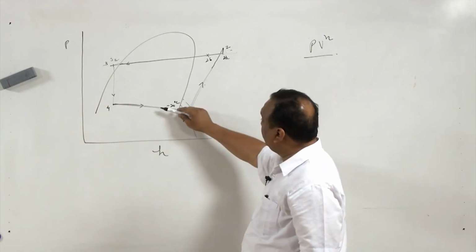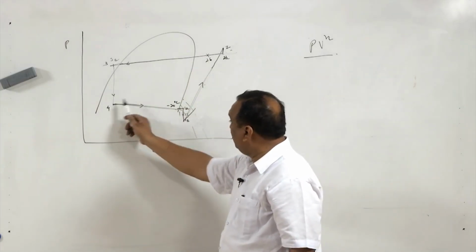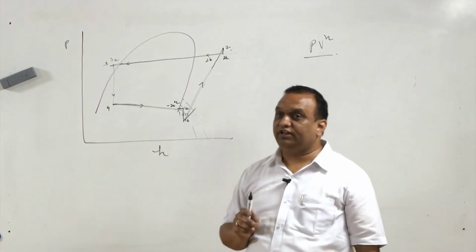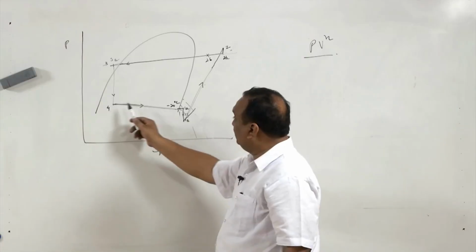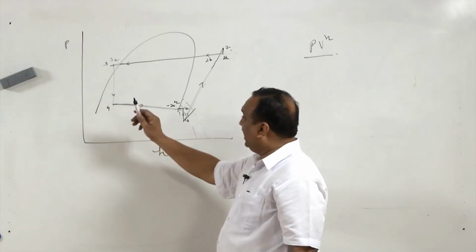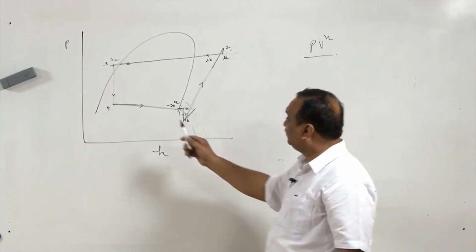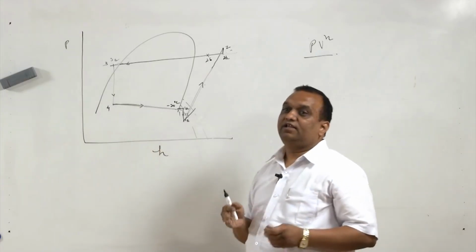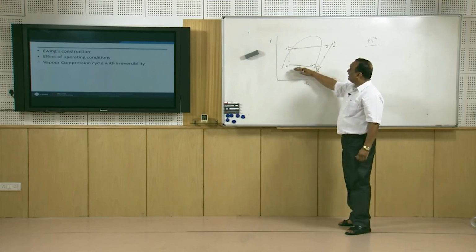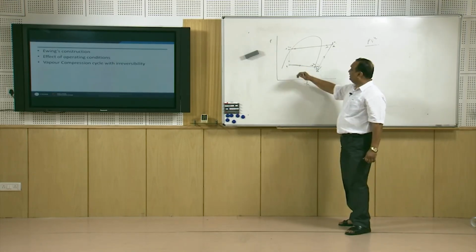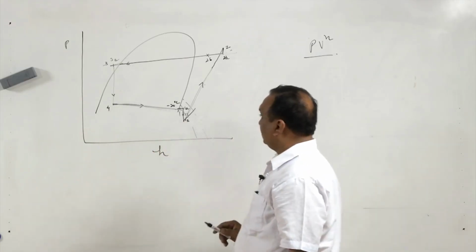Here, in both the evaporator and condenser, the pressure drop is taking place, but in 4 to 1 the pressure drop is more severe, or more of concern, because here the pressure drop is due to friction in the flow and there is also a pressure drop due to momentum, because the fluid is getting vaporized and picking up kinetic energy at the expense of the enthalpy of the fluid. So, they have a cumulative effect and there is a large pressure drop in the evaporator.